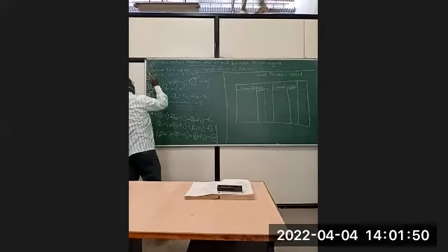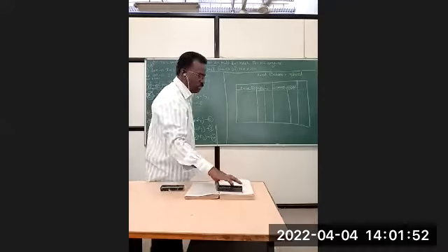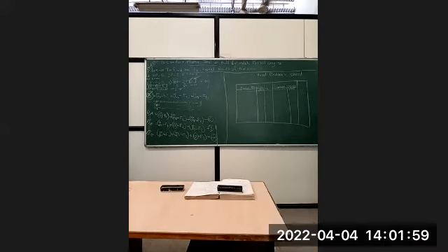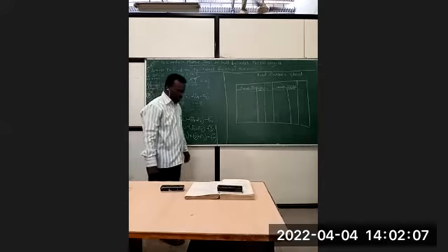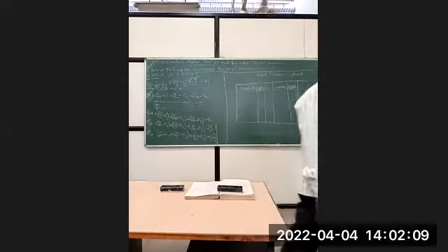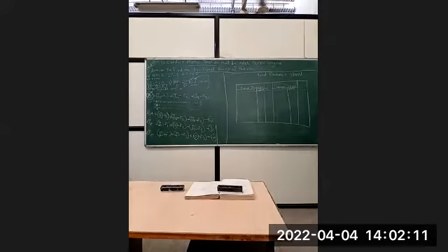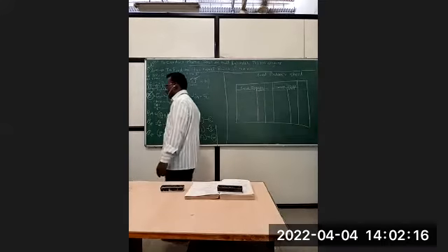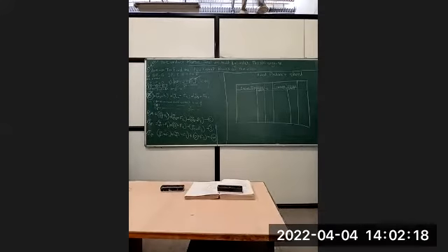Okay, thank you. So yesterday we discussed the Morse test, wherein we were supposed to find out the frictional power of the engine. For that, we alternatively cut the supply of the spark from the ignition system. That is, the spark plugs were not fired alternatively, and correspondingly we found out the brake power of the engine.